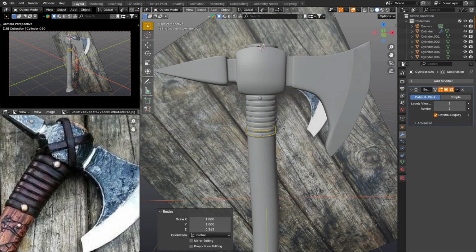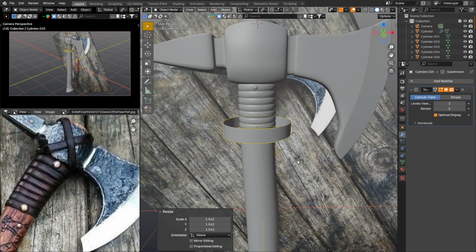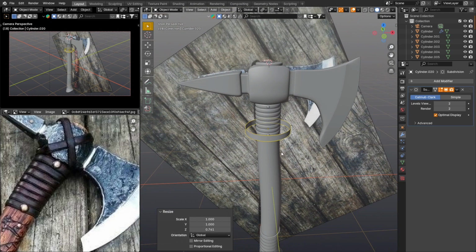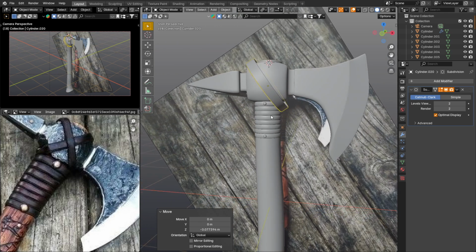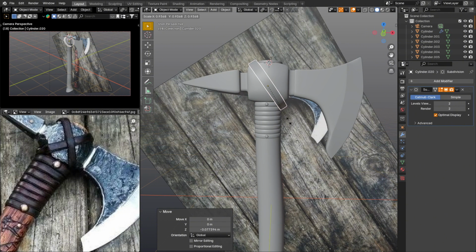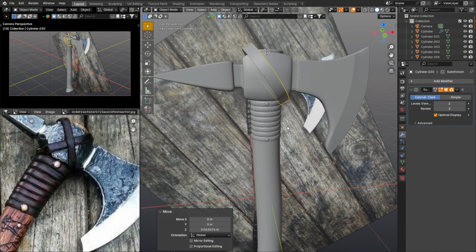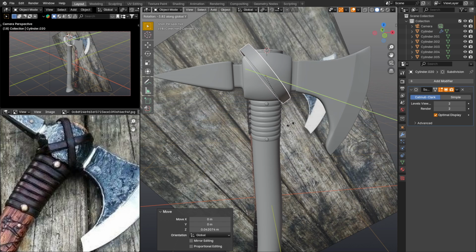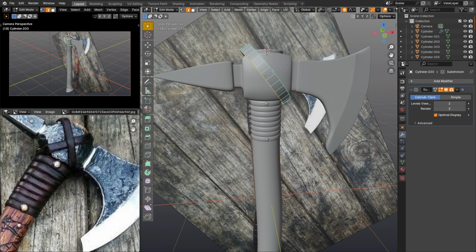Reduce it along the Z-axis. Increase it in diameter, to the size so that it is slightly larger than the central part around which we will wrap it. Rotate relative to the Y-axis. Place the element as much as possible as we want it to be in the future. It is even possible to shift the edge loop a little in edit mode so that the topology of the object is supposedly at an angle.